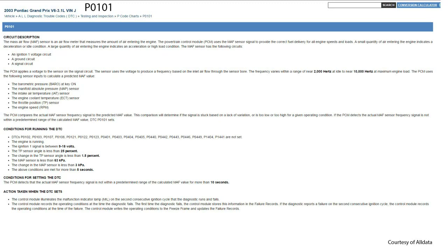What else? Well, then you got your TP angle. It's got to be less than 25%. So practically it's looking at idle or a constant, like cruising down the highway, you're only at maybe 12% TP, something like that. Nice and steady. Then, of course, it does not want to see a TP change of more than 1.5%. So it's really looking for steady on that TP.